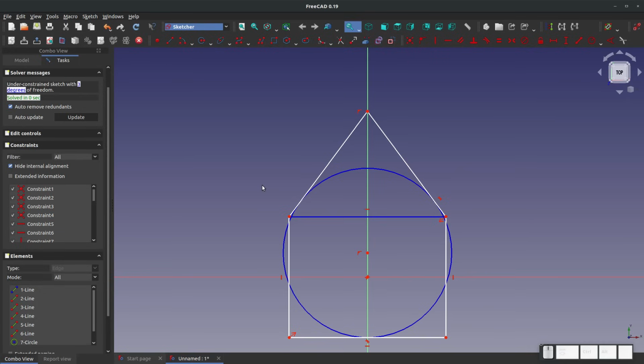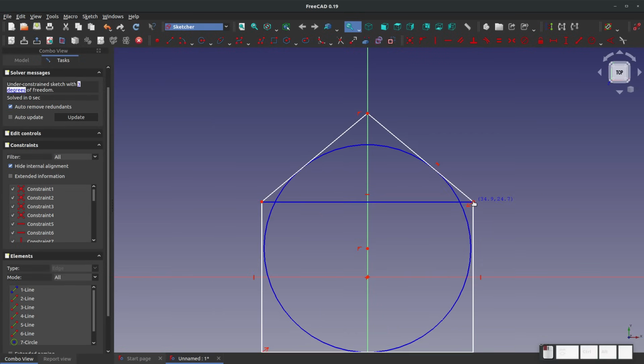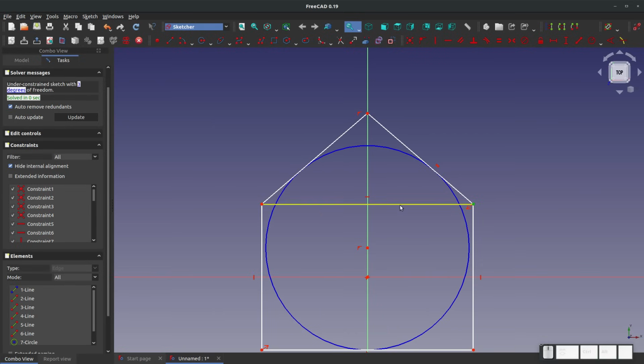All right, what other sketch tools are useful? Sometimes I might say, I just want to lock this point down and I don't care about what dimensions it's given, just as long as it's locked down. I'll select the point that I wish to lock and I can hit this little lock button and it automatically just gives it the vertical and horizontal dimensions that it needs, right? So it constrains that point.